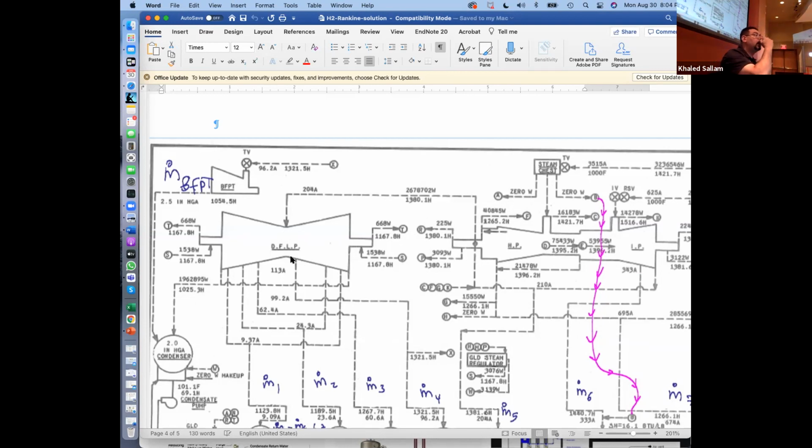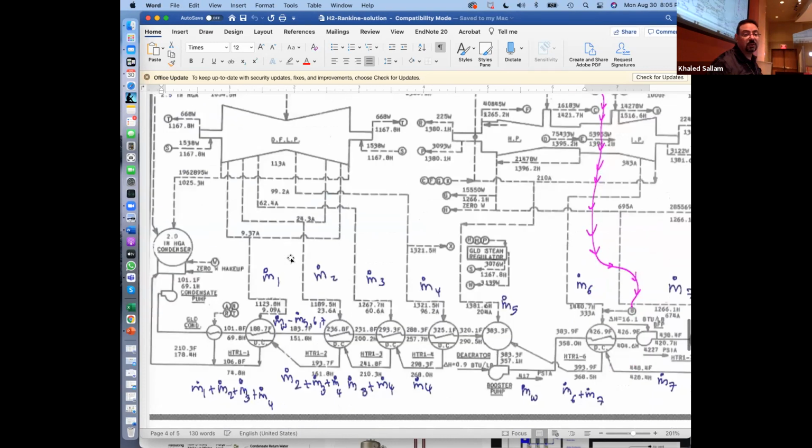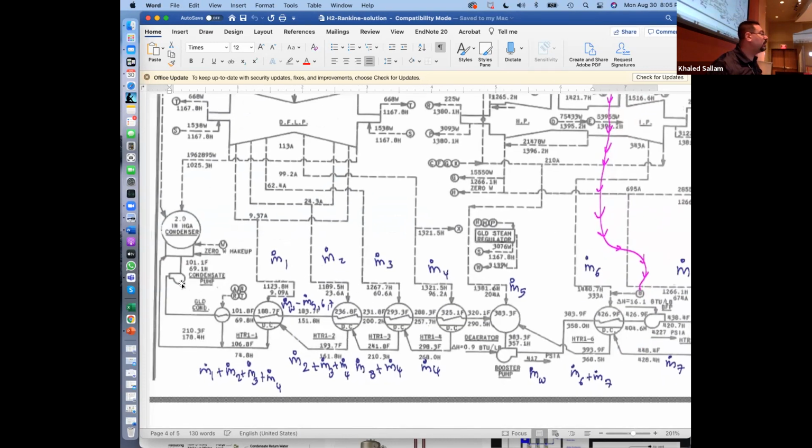It becomes a nightmare. Specifically, you need to calculate this pump work, and you don't really know what the pump work is. I mean, you know the delta H is done on it, but the pump work has efficiency associated with it. So the fact that the pump takes you from this H to this H doesn't mean that the pump actually used this delta H. It used more.